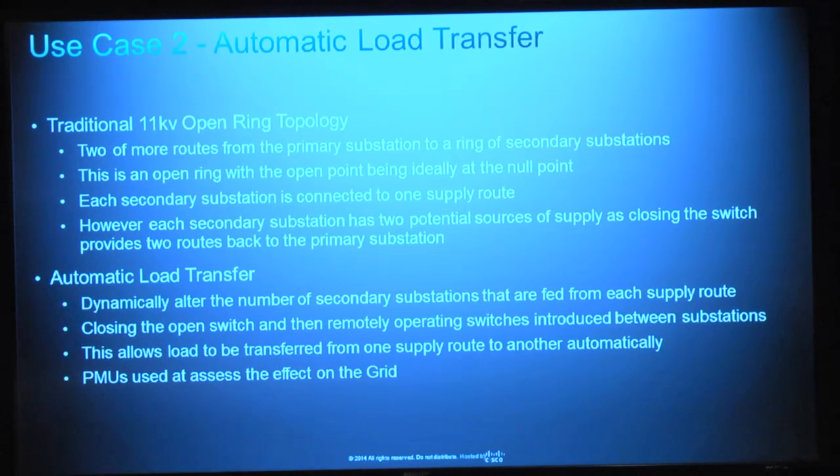That decision would not be based on time, it would not be based on operator intervention, instead it would be based on measurement, based on the data of what was occurring in the network to optimize it at the time. Basically, what they were hoping to do was to remove the need for the operator to be involved in this process, to remove the need for time-scheduled activities to take place, to put it back to the SCADA system to make an intelligent decision based on the measurements that were being taken.